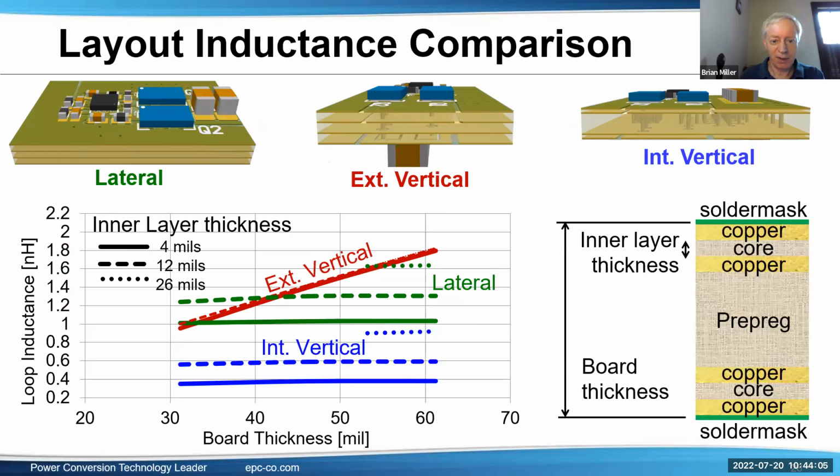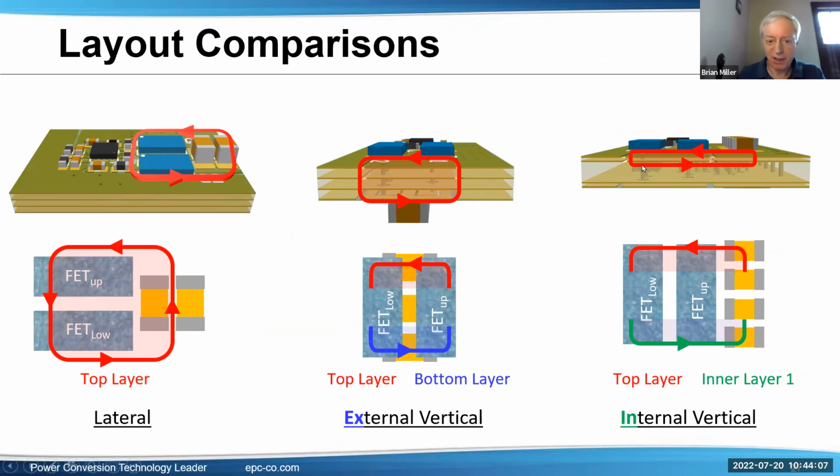I think the question is, once again, adding copper below the switch node, which in effect creates capacitance on the switch node. I guess there's two answers. One is the current. Typically, there's an inductor there, so the current doesn't change right away on the switch node. But I think you meant more voltage. So